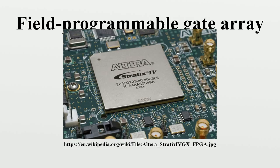Where previously a design may have included 6 to 10 ASICs, the same design can now be achieved using only one FPGA. Advantages of FPGAs include the ability to reprogram in the field to fix bugs, and may include a shorter time to market and lower non-recurring engineering costs. Vendors can also take a middle road by developing their hardware on ordinary FPGAs, but manufacture their final version as an ASIC so that it can no longer be modified after the design has been committed.